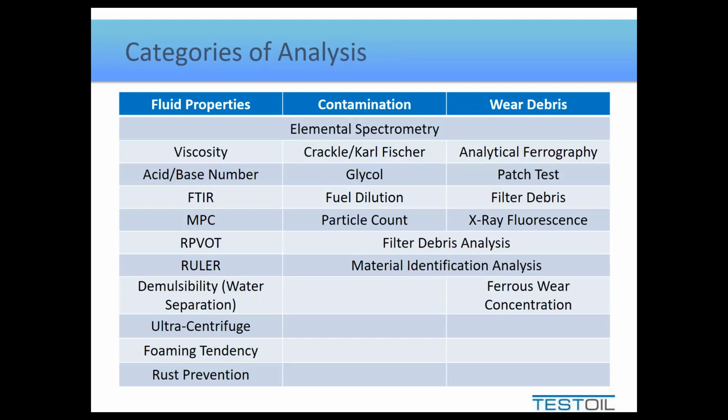Basically, you're either measuring fluid properties, contaminants, or wear, and this is sort of how they break out. As you can see, there are a couple of tests that branch into two categories and one test that covers all three. So today's webinar is focusing on a little bit of the contamination and in the wear debris section.